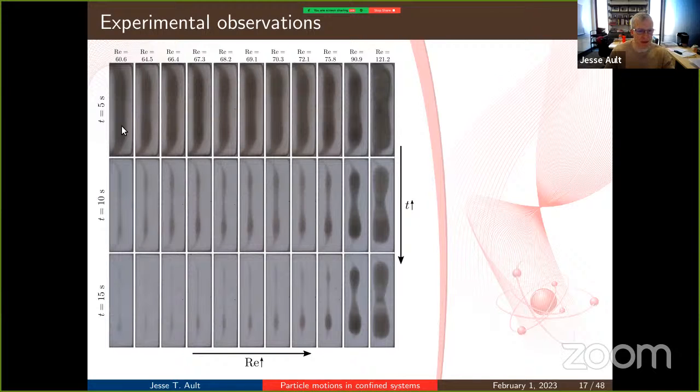But the interesting thing is, as you increase Reynolds number, you start to see some dye remaining over longer and longer timescales. And then especially at the highest Reynolds number, you see these very strong regions where dye is just captured. So it's no longer being flushed out, it's actually diffusing out. So if you continue this on for a very long time, they'll still disappear.